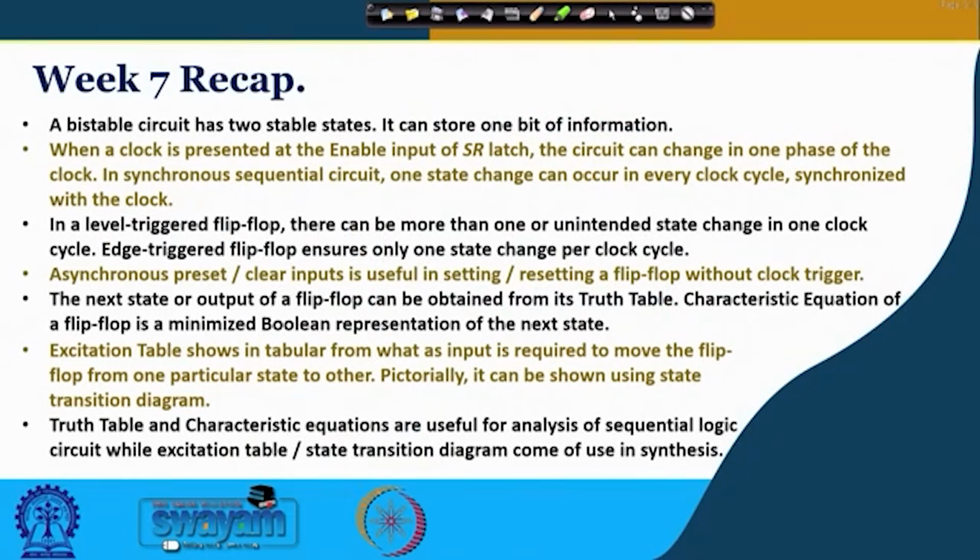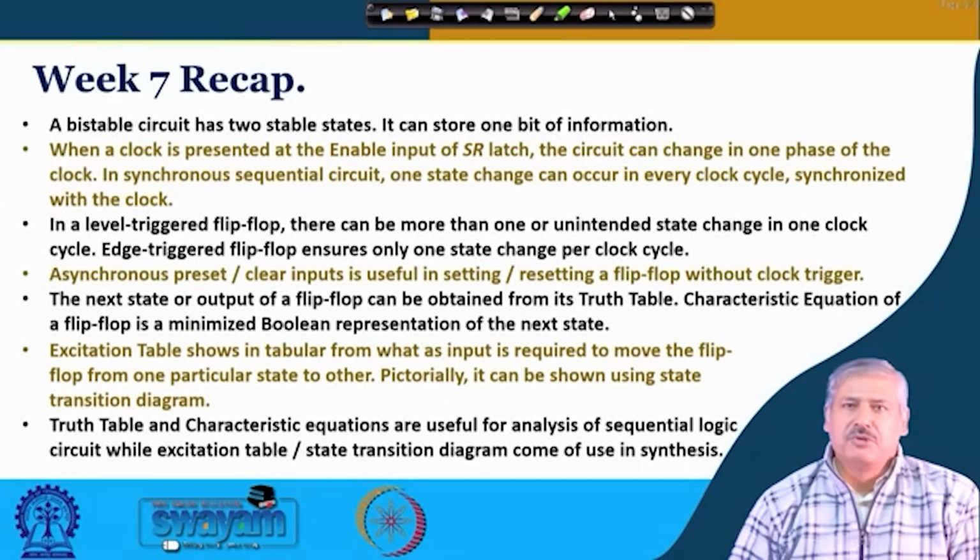So, if you remember, we discussed flip-flops in the previous week, its various representations in the form of truth table, characteristic equation, excitation table, state transition diagram, and then we understood the issues that could be there with level triggered flip-flop, for which edge triggered flip-flop is advisable, which ensures only one transition per clock cycle.